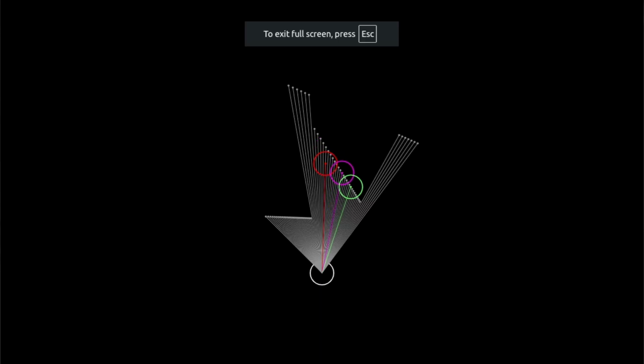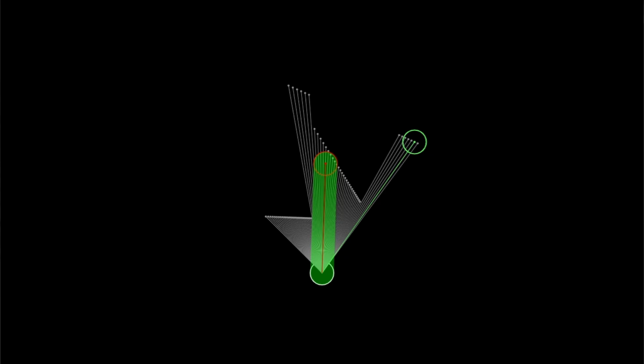For basic obstacle avoidance, we are using a disparity check algorithm, which is a modified version of the follow the gap algorithm. What it does is it throws around a bunch of circles, and whichever circle moves to the furthest distance, it targets that circle, and that is its target angle. It has a few drawbacks. For example, it has a tendency to move to the corners of the tracks, but we solved that problem. So now it's working really fine for us.